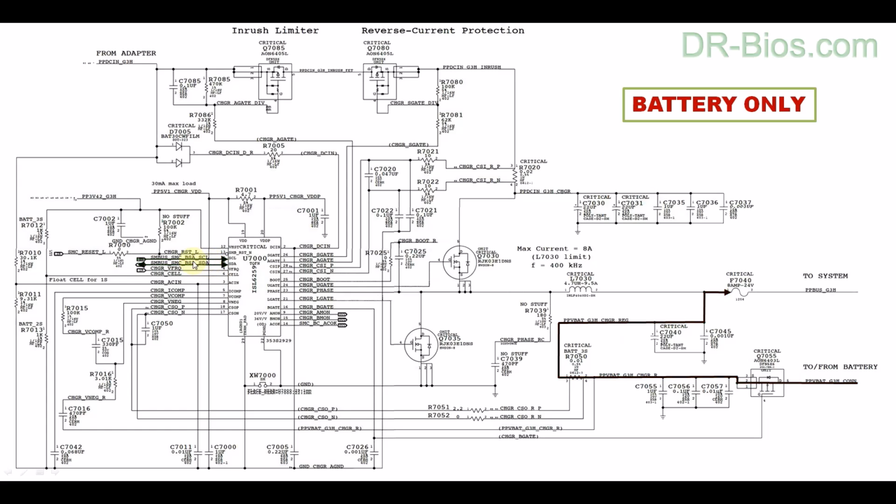In the next step, SMC that has received PP3V42_G3H voltage, also SMC_reset_L signal, but as it hasn't received ACOK from charging IC, it realizes that adapter is not plugged in, and 3.42 volts that entered it is generated from battery voltage.